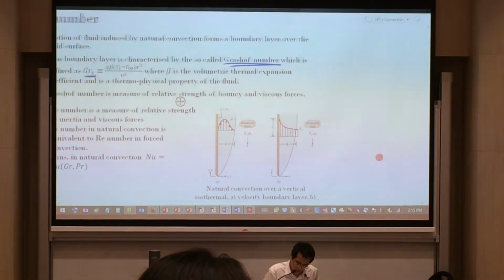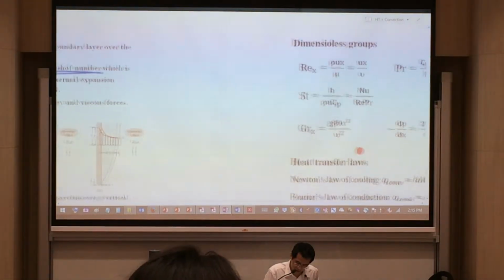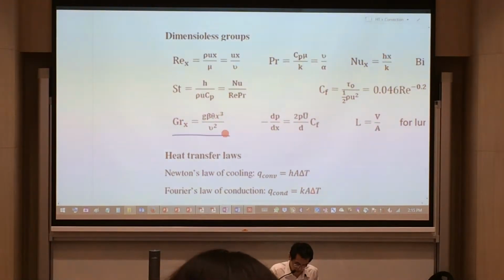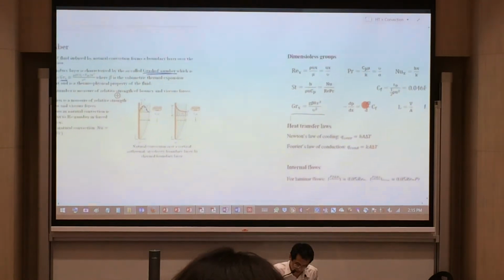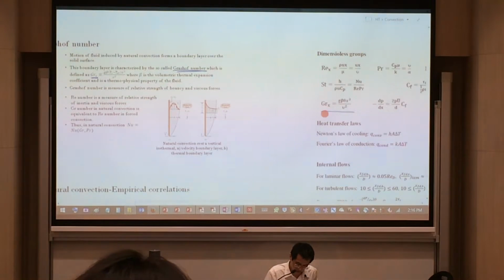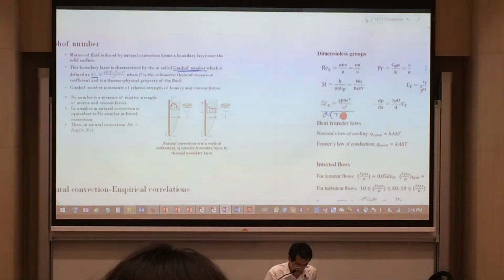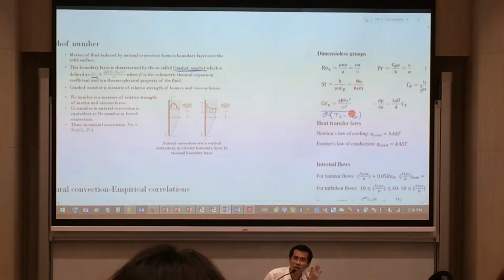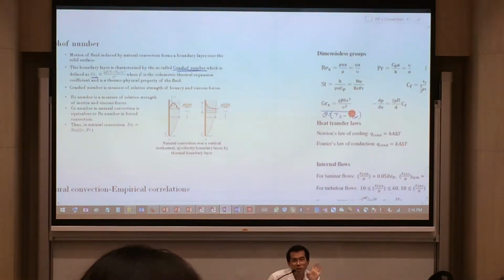I'm going to slide over to what you could see in your latest exam data booklet. Your Grashof number is written like this. If you make a comparison, you would see that the theta over here is actually represented as Ts minus T infinity. You have to note this because it's not explicitly written as Ts minus T infinity, and it also depends on which one is hotter.